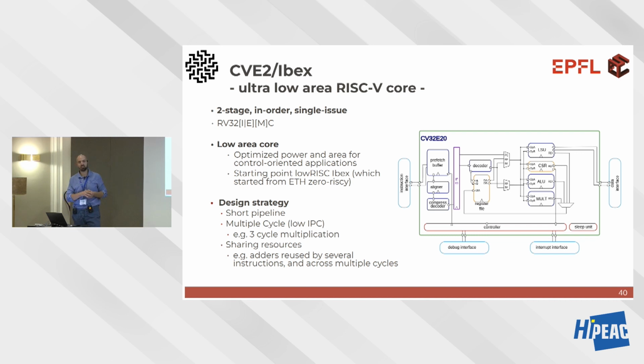But those are parameters that you can plug and play. You don't necessarily have a single fixed design with no parameters, so you can decide whether to have 16 registers or 32. Someone suggested using 16 registers. Yeah, that's what we did. And to have or not the multiplier and the divider in the ISA. So like this, you have 2 parameters, 4 possible cores, if I'm not wrong. And that makes an IP that can be configured in 4 different ways, that you can then select depending on the profile, knowing that the design philosophy behind it was a wake-up core, a guy waiting for an interrupt.